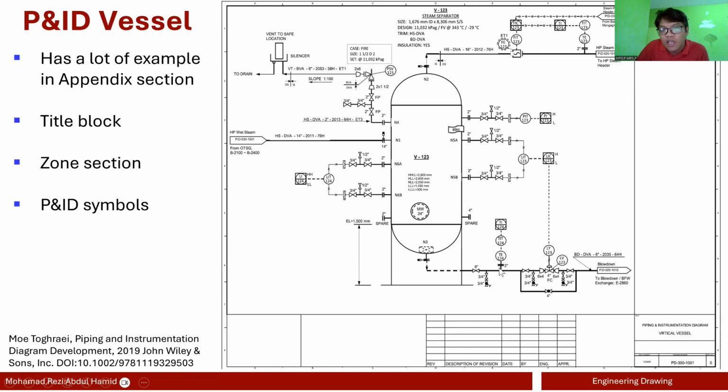And then these are flanges where you will have a temperature element, 1 to 4, to detect the temperature of this particular line. The element will send a signal to the temperature indicator transmitter mounted on the unit, because it's just a circle. And then they transmit the signal. These are dash lines. The dash line here is an electrical signal sent to the DCS to show the temperature at the DCS.